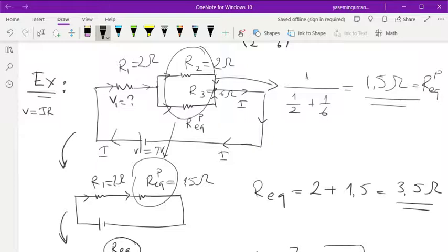So in that case, you're going to find what is the V1 on that R1. I was 2 ampere, R1 is 2 ohm, therefore voltage on R1 is going to be 4 volt. And so, which tells you that because the total voltage is 7.